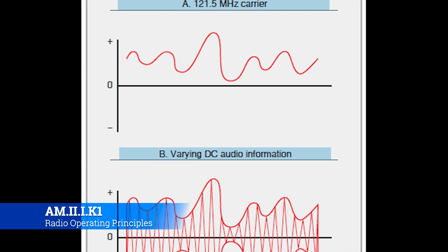To transmit and receive useful information, this wave is altered or modulated by an information signal. The information signal contains the unique voice or data information desired to be conveyed. The modulated carrier wave then carries the information from the transmitting radio to the receiving radio via their respective antennas. Two common methods of modulating carrier waves are amplitude modulation and frequency modulation.